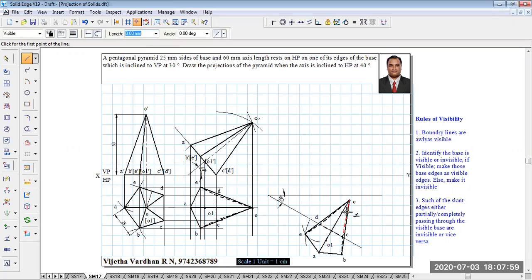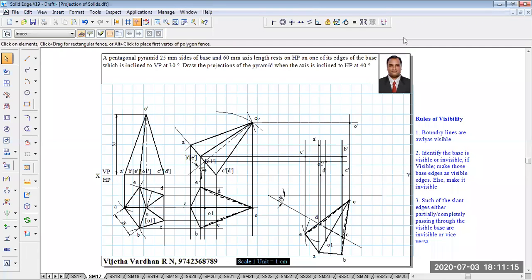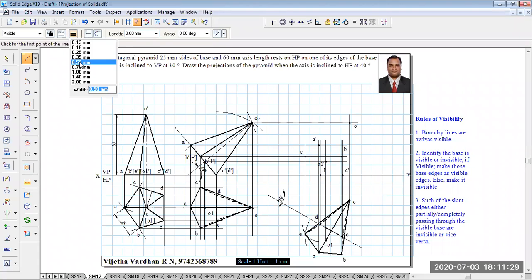In the same fashion, we have to do it in the third stage front view, for which let me draw a vertical projector for the apex position first and the horizontal projector from the apex position of the previous stage front view like this. Now the intersection is going to mark it as the apex position O dash. In the same fashion, the base corners have to be obtained. Now let me complete the same and show it to you. Okay guys, now you can see that I have completed the paths by drawing the projectors, and I have mentioned the ABCD. And now what we have to do is complete the front view.